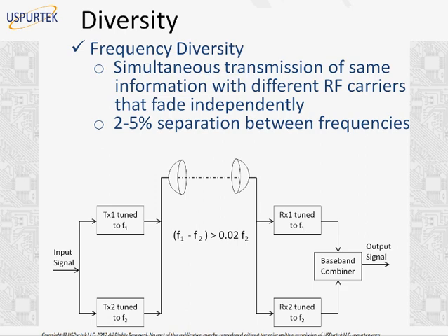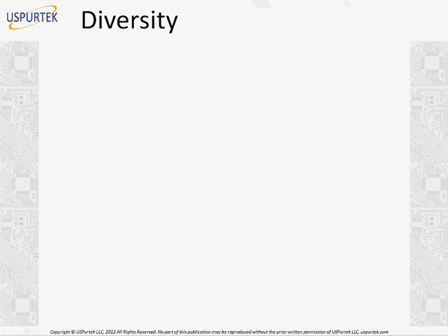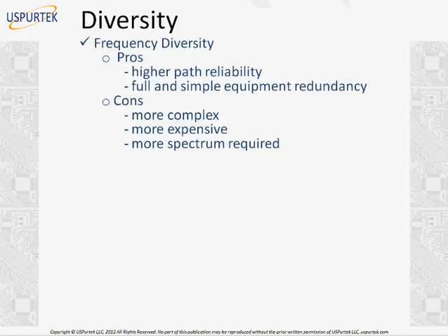Now, just note this point: fading independently is very important. If they don't fade independently, then you don't achieve diversity. And to achieve that, there must be 2 to 5% separation between the frequencies.